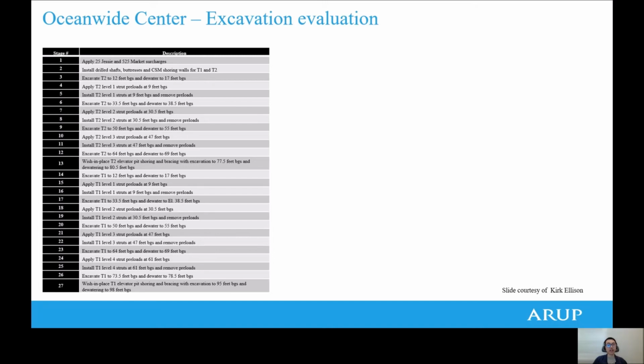So it's a very complicated process, where the sequence really affects the response of the simulation model. This basically requires that, when you do the simulation, the model can do the same kind of sequence realistically, which is removing some part of the soil domain, preloading some beam elements at some point, and changing the water table at a certain time in a certain way.